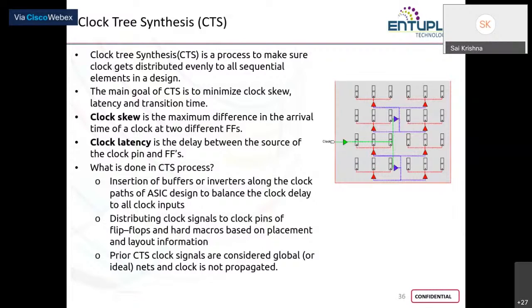Now if the same applies for a clock, that creates a confusion for your timing analysis, as well as the triggers being delayed or early. So that's why what we do is, in clock inverters especially, you increase the width of PMOS. Excuse me.